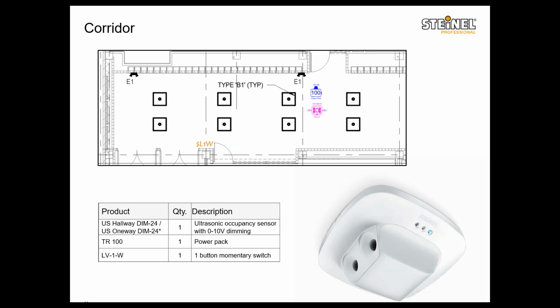Logan, there was a question about a minimum dim percentage. Can you speak to that? The minimum dim percentage would be 10% on our smart app. But really the fixture is the deciding factor on the minimum dimming, because the driver of the fixture decides its minimum rating.